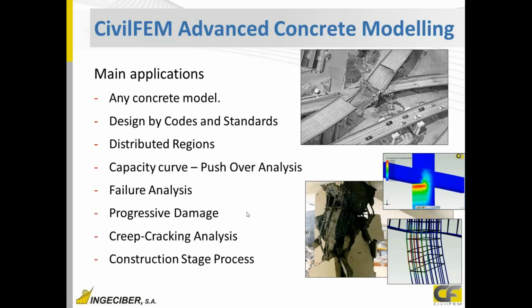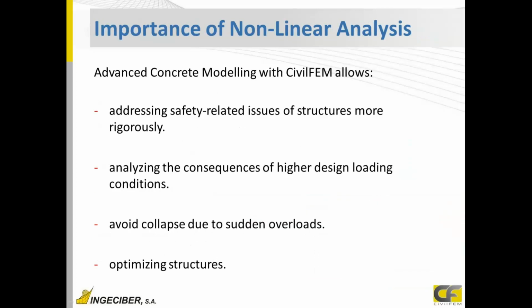And it's very important to analyze models also under nonlinear analysis, not only linear analysis and code and standard verifications, because in this way, as we saw, you can address safety issues of the structure, analyzing whether they are brittle or ductile.